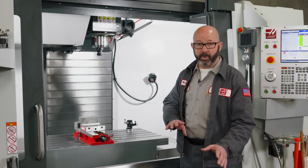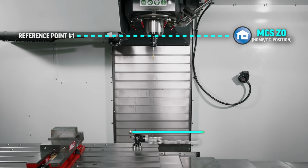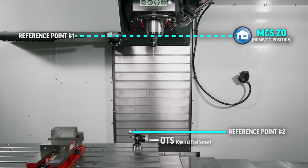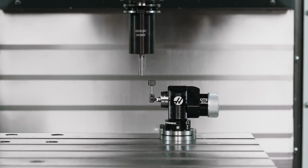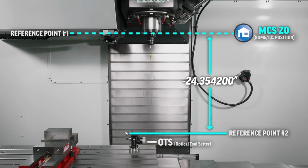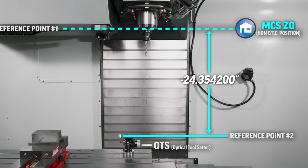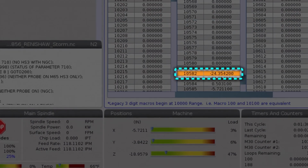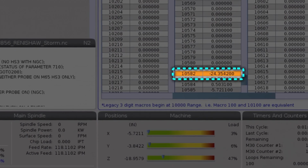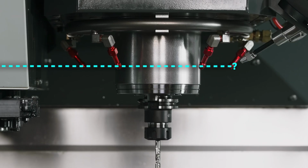Our second reference point is right here, at the top of our optical tool setter, our OTS. Now, during our probe calibration process, the control figured out the exact distance from our spindle to the top of our OTS stylus and stored it for later reference in macro variable 582. Now, just saying from our spindle is pretty vague, not precise at all. I mean, are we measuring our spindle from here or from here?